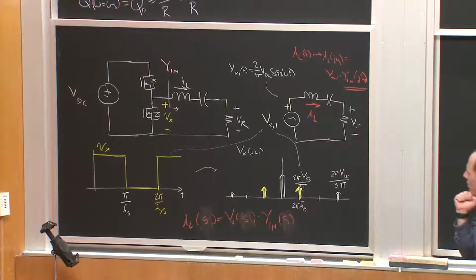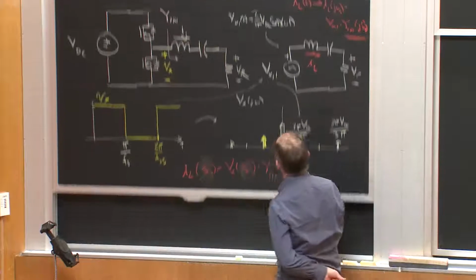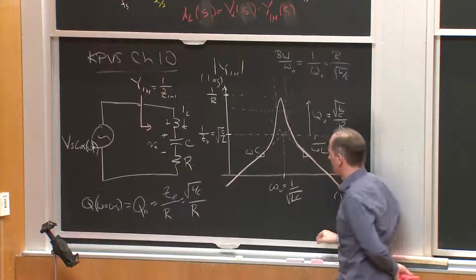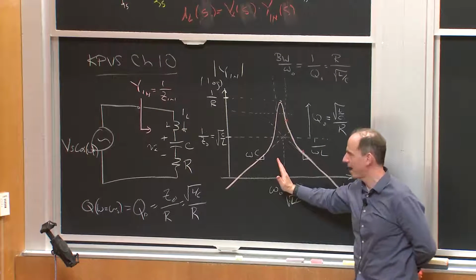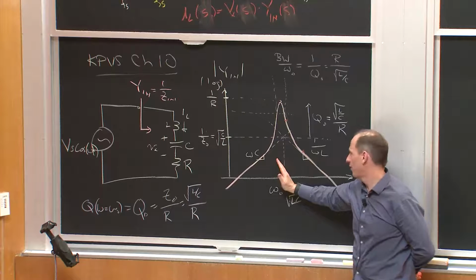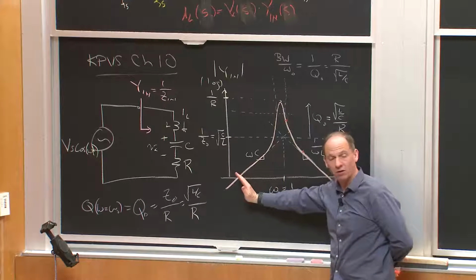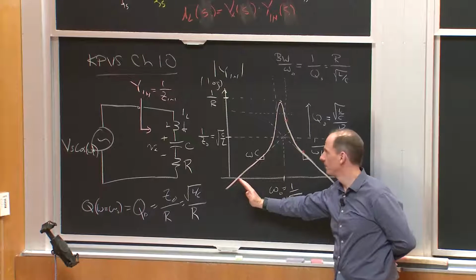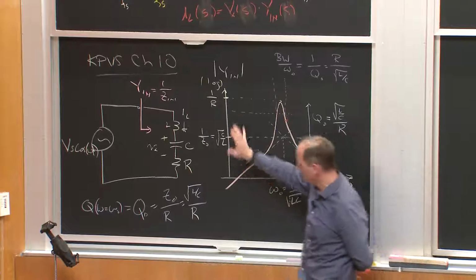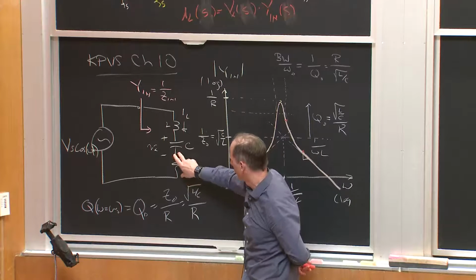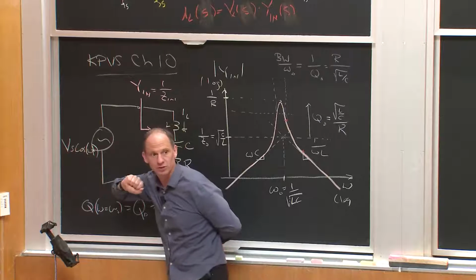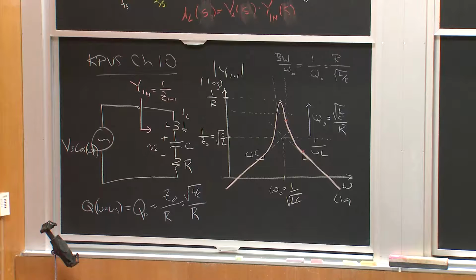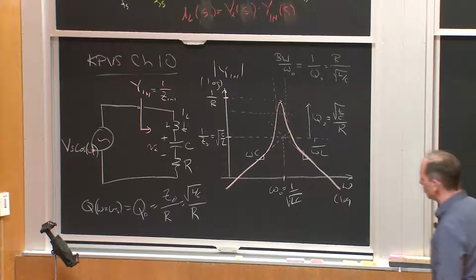We could modulate power by going in either direction off of resonance, right? According to this, if I put my switching frequency right here, I'd get maximum power for a given voltage. And if I go in either direction, the admittance goes down and I get less power. And the maximum voltage I can apply with this particular network is that the voltage across the resistor is equal to the input voltage, or I should say the fundamental of the input voltage. Okay?